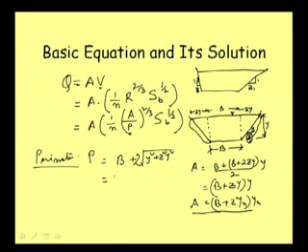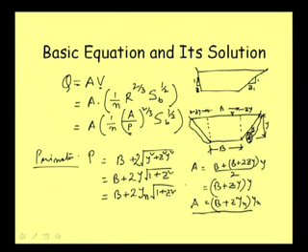So that will be B plus twice y square, bringing y out of the root sign, we can have y root over 1 plus z square. Well, and then again writing for uniform flow, we can write B plus twice y n. This is nothing but, writing in a symbol that it is normal depth, root over 1 plus z square. Well, so like that we can have our expression for perimeter and area.